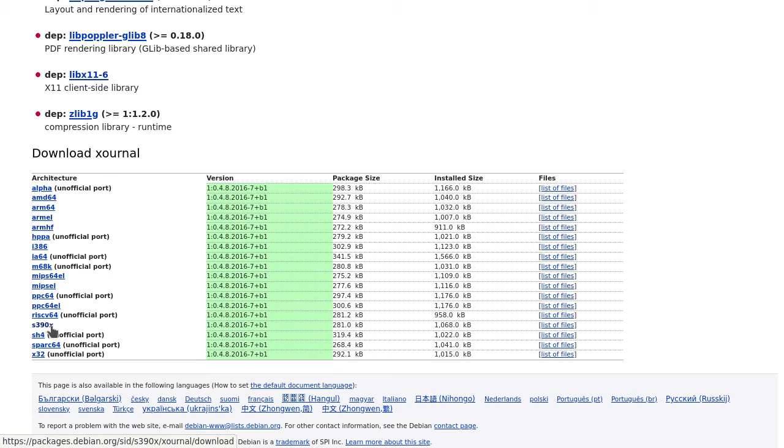A RISC processor, on the other hand, is trying to optimize the use of the transistors. Even though one instruction doesn't do nearly as much as one from the CISC processor, and you need quite a few instructions to make up for one of the other, from the energy perspective it is actually more energy efficient. That's why most data centers make use of RISC processors and not CISC processors. The x86 is a prime example of a CISC processor. So is that giving you a general picture about CISC versus RISC?